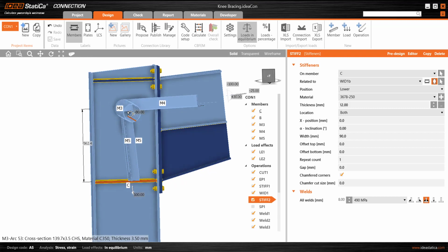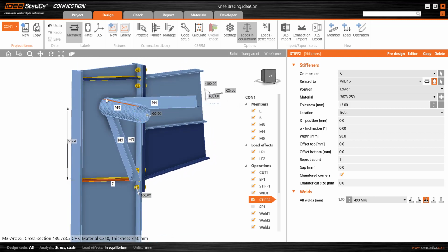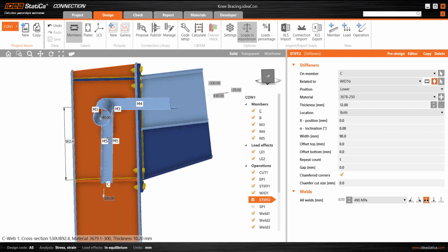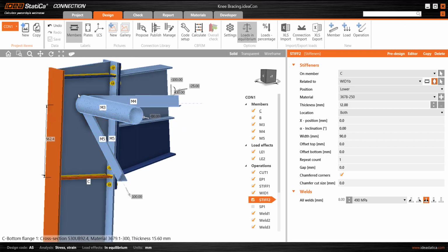Now, moving on to the bracing connection details, let's have a look. I'll firstly create a gusset type connection of the strut to the web of the beam. I want a vertical gusset because I want to attach the leg of the angle to that, the wall bracing. I want to use the same cleat and have that gusset as a common element for both of these members here. And then I want a separate member here. So of course it depends on what you're looking for here.